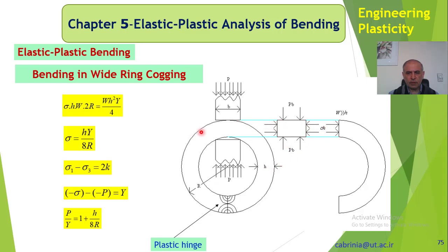It's only in this plane here. The material can flow only in here. It cannot flow perpendicular to the screen when the ring is wide, because that width gives us enough material so that the material in the width is some kind of like a rigid material. It doesn't let the material move perpendicular to the screen.